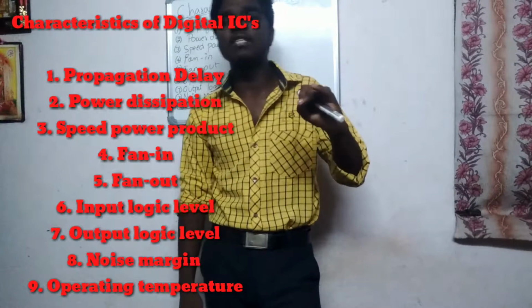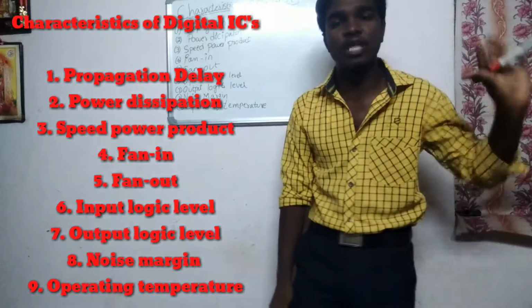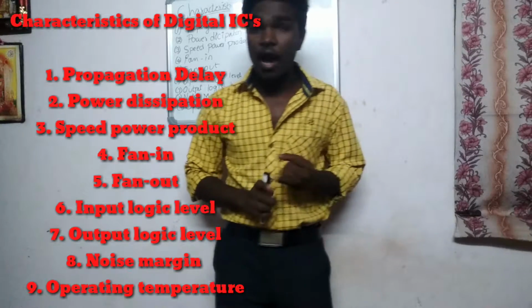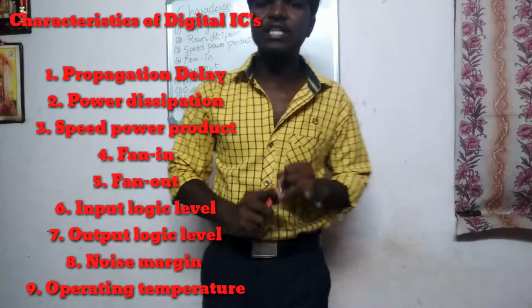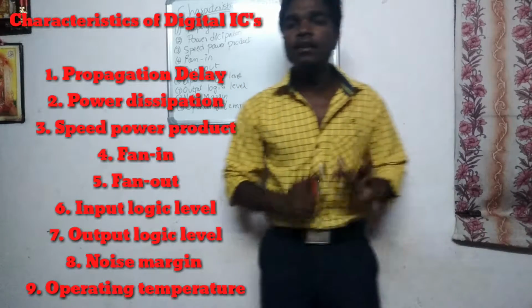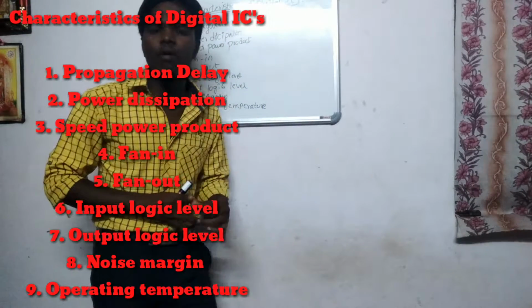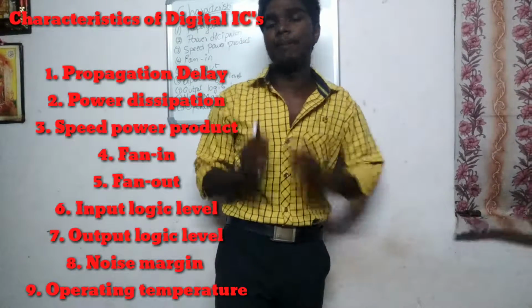The topics that I am going to cover in this video are specifications of digital ICs, TTL circuits, TTL NAND gate, CMOS NAND gate, and ECL circuit. First topic, specification of digital ICs or characteristics of digital ICs. There are a total of 9 characteristics of digital ICs. They are propagation delay, power dissipation, speed power product, fan in, fan out, input logic level, output logic level, noise margin, and operating temperature.